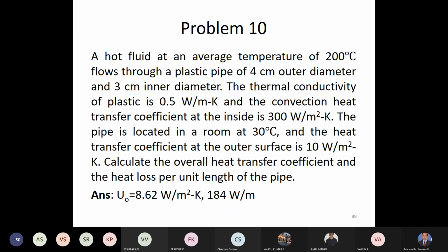And also on the next page, page number 165, you have what is called the fouling resistance. What happens is whenever you are using a heat exchanger with water flowing through it for a long period of time, some scales form because of the deposits and the salts. It could be mud deposit or it could be salt. Often you notice that when you are servicing your geyser in your bathroom, over a period of time, there will be some scale formation.